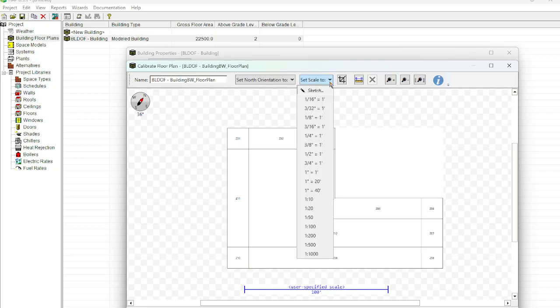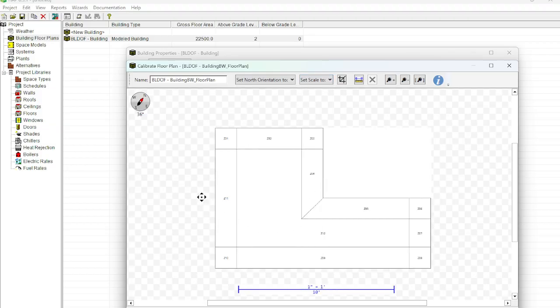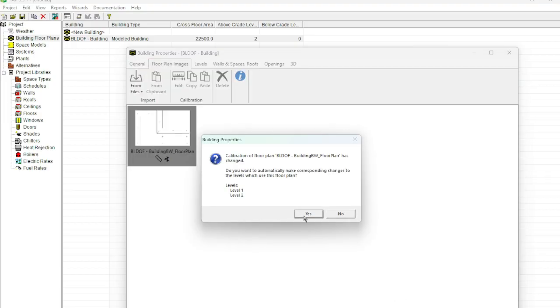All right, set the scale. We're going to set what it defaulted as. Scale is 100 feet. Let's set it to 1 inch equals 1 foot. Okay, then we have a scale to it. All right. That's still not what I wanted to get back to, but it is things that you need to know. So you can say OK on this.